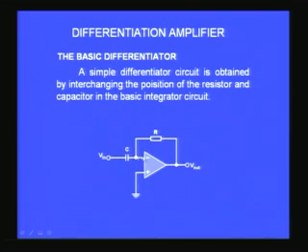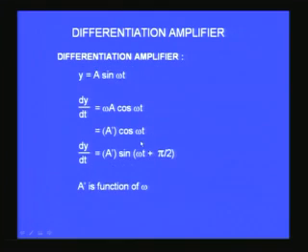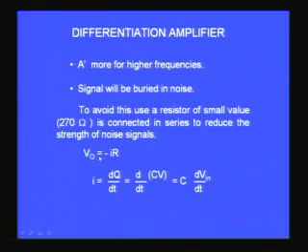I will explain in more detail about what the input bias current is all about later on, but for the moment imagine that the current actually passing through the amplifier is going to be very, very small because of the large input impedance associated with the amplifier, and therefore almost all the current flowing due to the AC signal applied through the capacitor will only travel through R, the feedback resistor, and therefore V output is nothing but I into R, where I is the current flowing through R. This voltage is going to be negative because the current is flowing towards the output from the ground, and that is why I say the output voltage is V output equal to minus I into R, where I is the current flowing through the resistor.